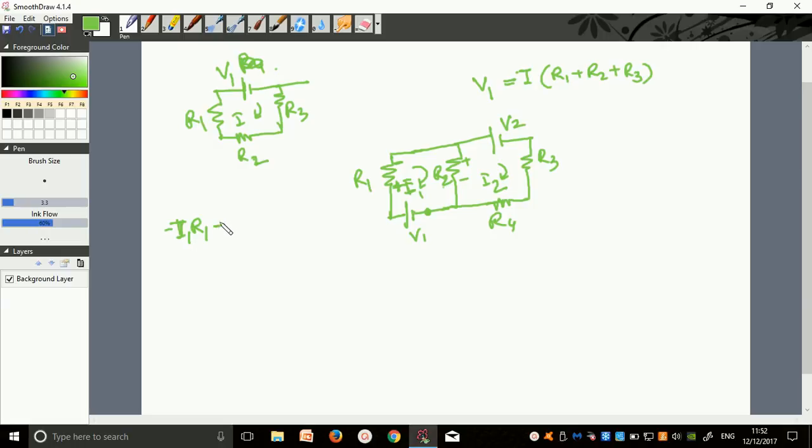So within R2 we will have minus I1 times R1, and within R2 we will have what is flowing through R2, I1 and I2. Because I1 and I2 are flowing in the opposite direction, I should write I1 minus I2. Remember, we are considering mesh 1, so I'll have to consider I1 as the first term, having R times I1 minus I2. When I'll be considering the same R2 resistance in mesh 2, I will write I2 minus I1. And then equals to, then negative to positive, it is going up, increasing. So I'll use a different sign equals to this. This will be my equation number 1.